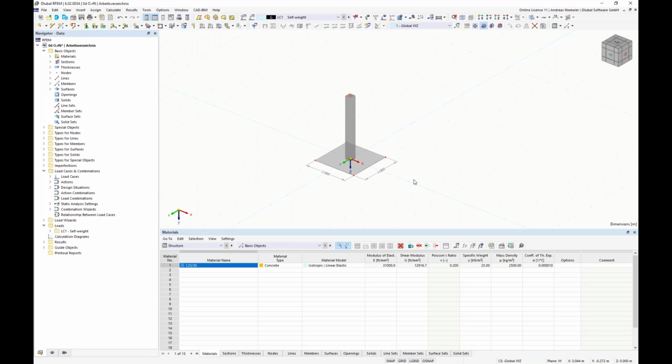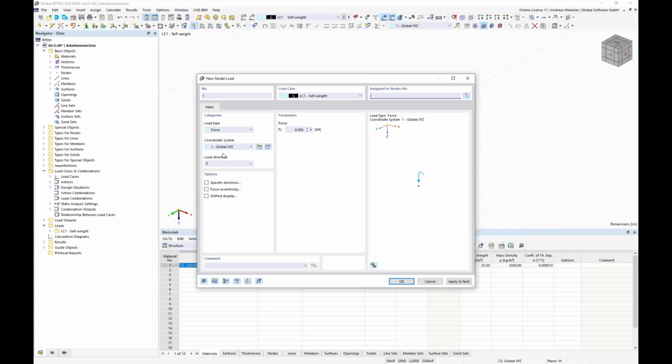Then what we know for such structure types is maybe the load, what they should overtake. In this case, we know the surface weight has to be overtaken. The surface weight is calculated according to the column size and length and the size of the foundation plate. What is open and can be bigger or smaller, the analysis will show. So surface weight is clear, plus, let's say, a horizontal force. For this example, I take it in X direction, but it can act also in other directions.